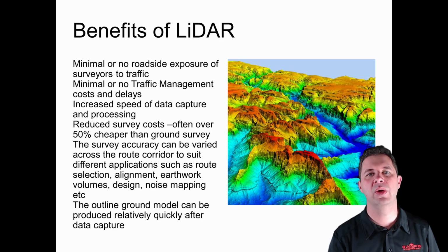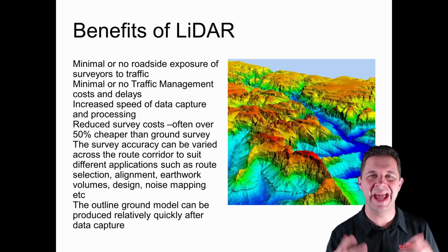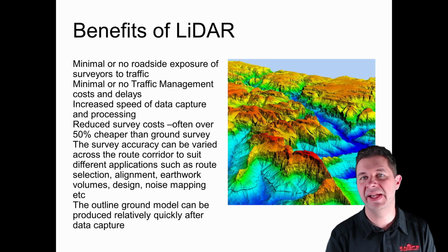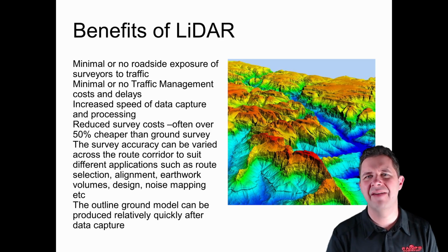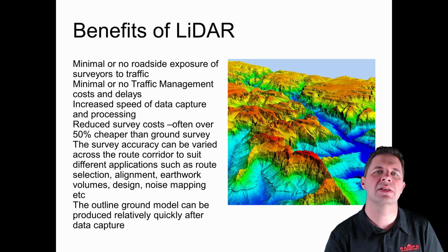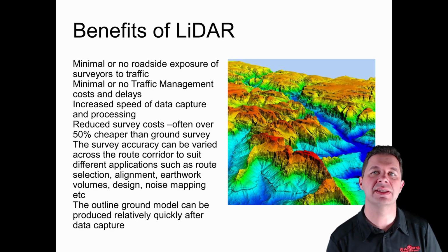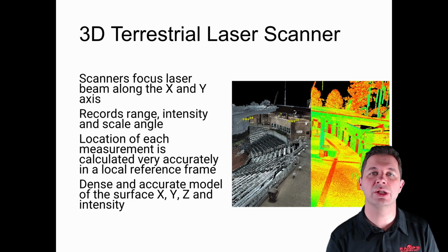These aerial surveys can be done quite quickly. It doesn't require access into areas that might be difficult or dangerous to access. Typically requires less people to perform our survey. And we don't have delays to traffic and people having to stand by the road with stop signs and things like that. So there's some real benefits if we can use something like LiDAR and do aerial surveys. Now, it's not just LiDAR in the air.